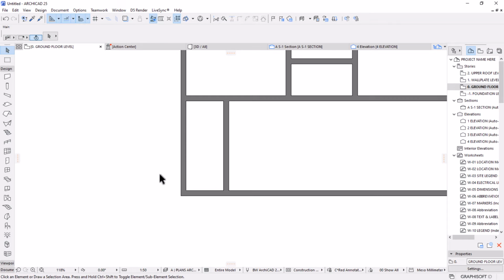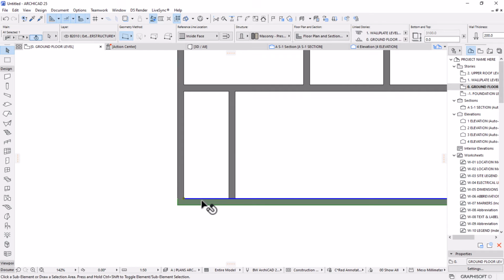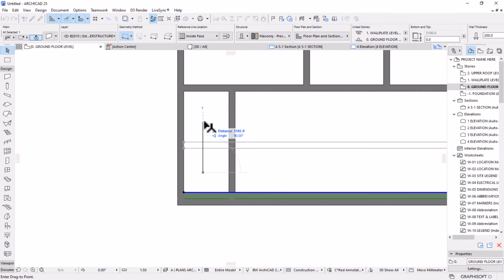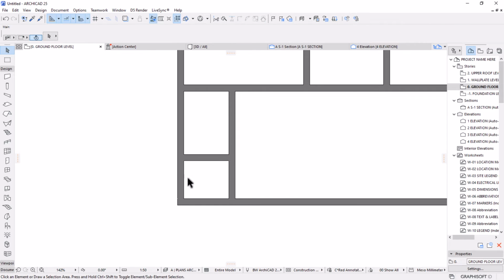So we also have a passage, more of a lobby, that will access this. So that you are not here just exposed, or the door is not exposed to different weather conditions. Obviously you want to protect the entrance of this. So I'm going to select this wall again and make a copy like that, and then Control D, move it by the width of the passage, which is going to be 1.2, and hold Control to activate this tool to trim it off.